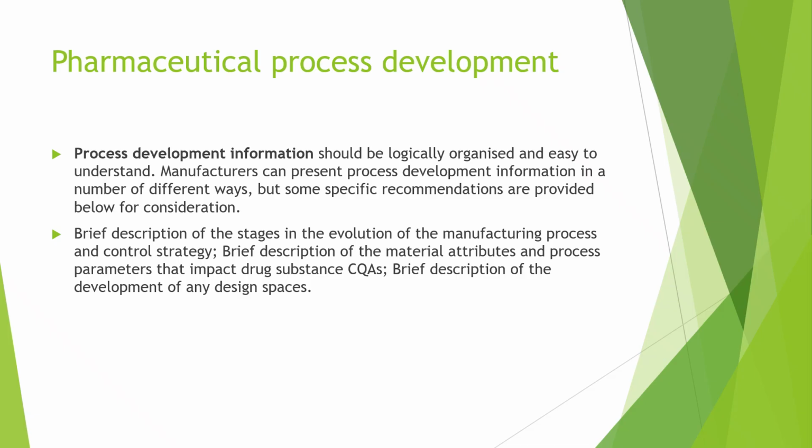And when that process is completed, the material will be unloaded. Then again milling if required for proper granules, then again sifting, and then blending, and then compression. So that type of logical sequence should be mentioned in the product development.